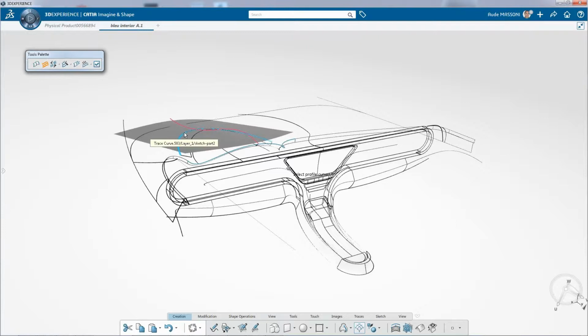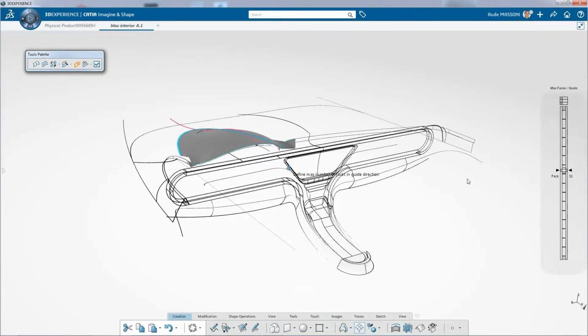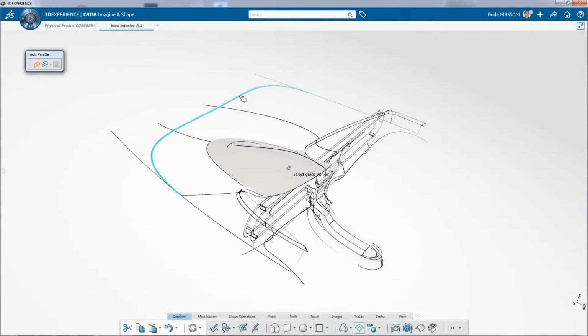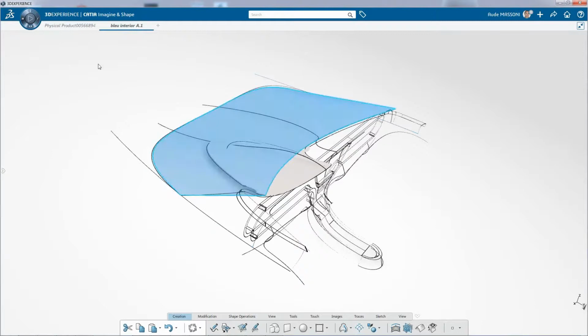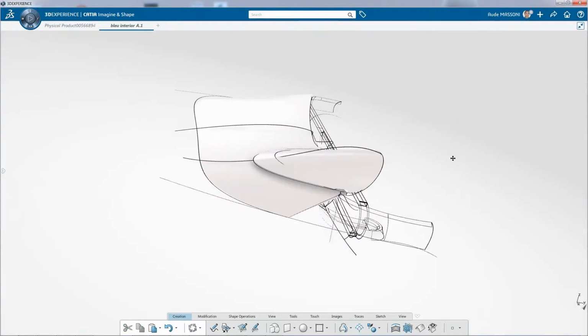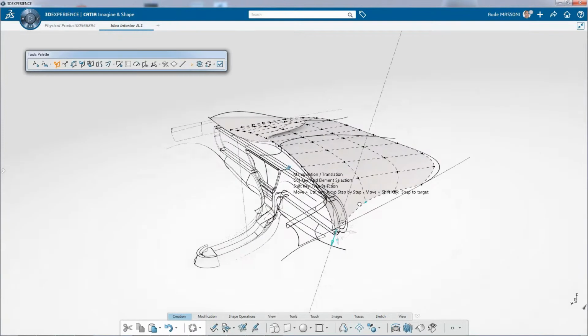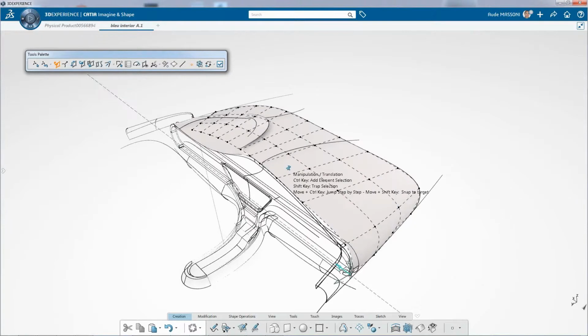And what we're going to do is, again, put a surface through 4 boundary curves, and then we increase the resolution to get it more accurate. You can see there's a slider bar here that increases the fidelity of that surface, so it kind of suctions to those curves. And at some point, we will let the 3D take over, and we can manipulate just pushing and pulling these control points of the subdivision surface.